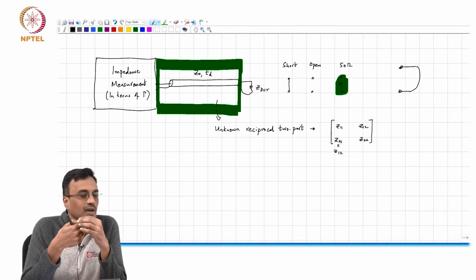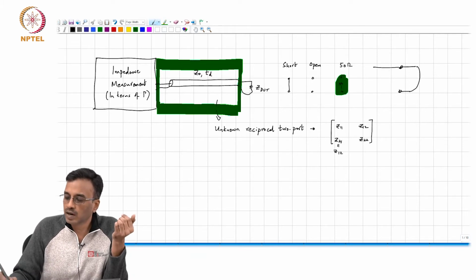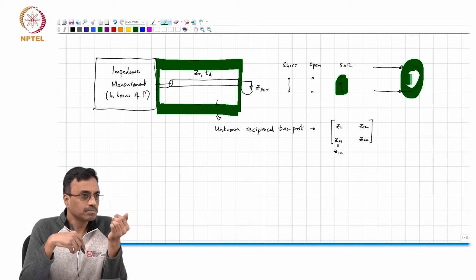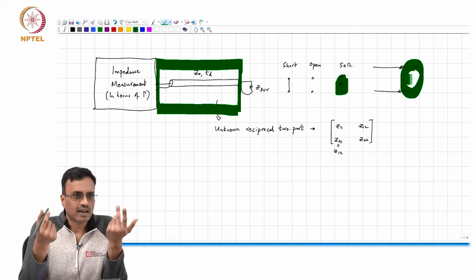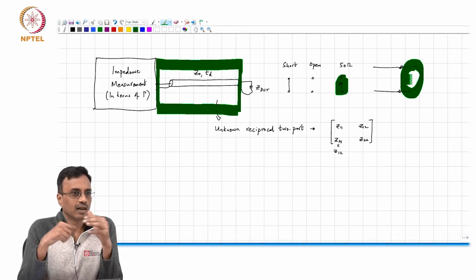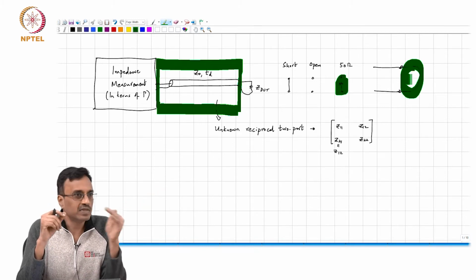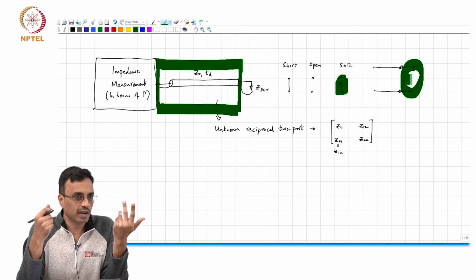Yeah, okay. So basically, as you can see, if you go and connect this to a transmission line, you have a loop here, and any loop has got inductance, which is equivalent to saying that as frequency keeps increasing, it is definitely a short circuit for DC, but as the frequency keeps increasing, it is no longer a short circuit, right?